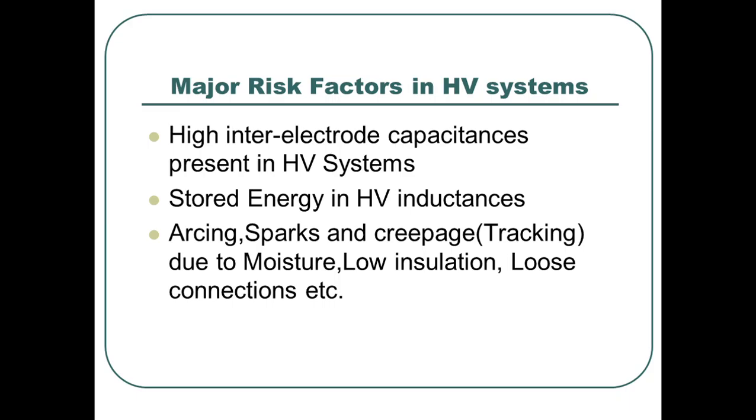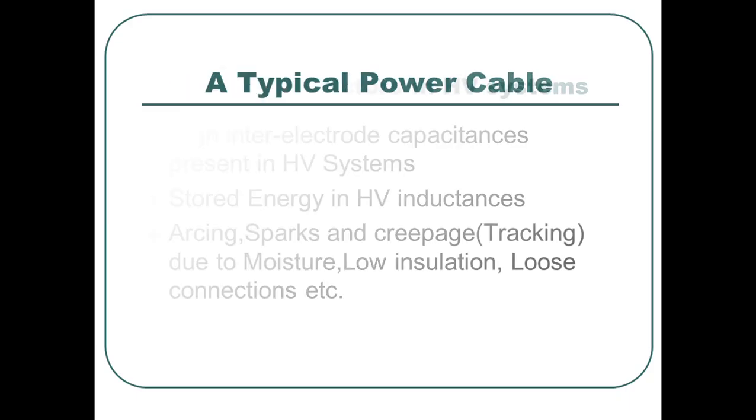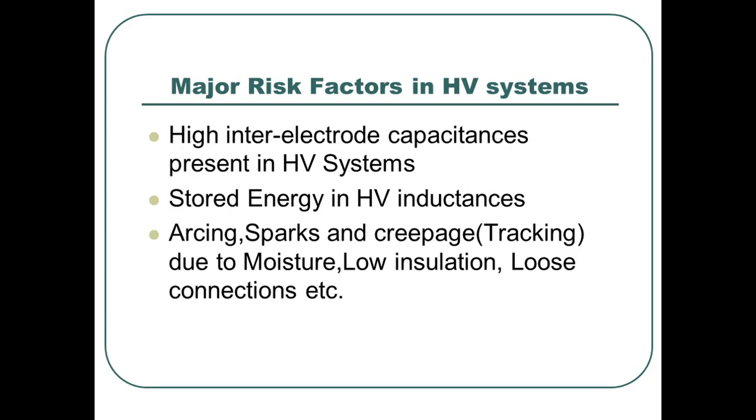What are the major risks involved in high voltage systems? When we speak about major risks: high inter-electrode capacitance present in high voltage systems, stored energy in high voltage inductance, arcing, sparks, and creepage, tracking due to moisture, low insulation, loose connections, etc.